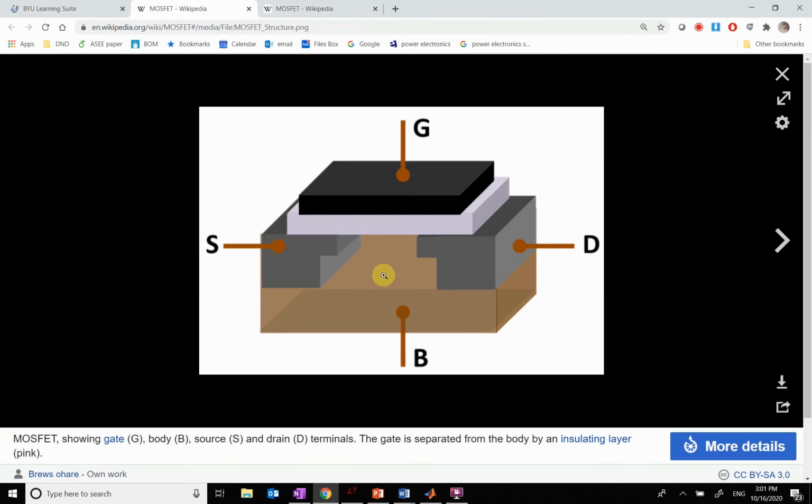So here is a MOSFET. It has an N region, an N region, and then it's grown with a P region in between. So it looks a lot like an NPN region, except in this case, the connection to that middle region is insulated by an oxide. It has a complete insulator, whereas with the BJT, this insulator was out and we made contact to that middle P region.